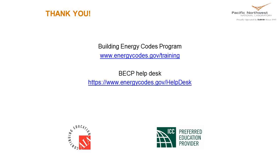Those U factors and the R values and the maximum come from the tables in Appendix A. The methodology we use to run compliance in the older codes, not so much 90.1 2013, but 90.1 2010, is Appendix C. Take a look at Appendix C. So it's a very good resource if you are showing compliance using ASHRAE or you want to know what those lookup values are, the U factors, then you'll want to get ASHRAE standard 90.1 and go back to the Appendix A and look at those.